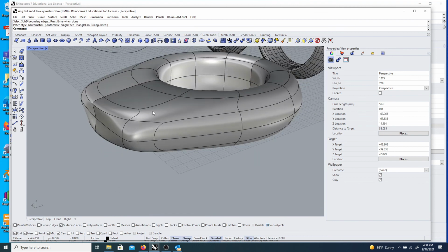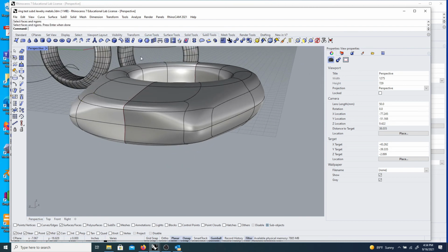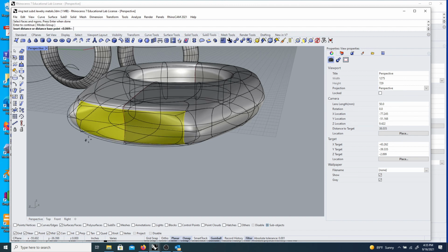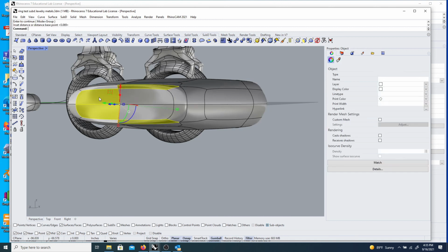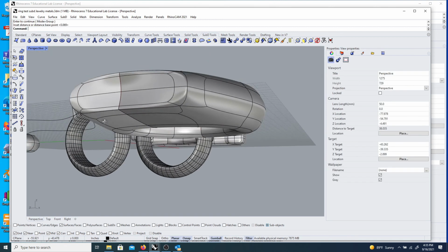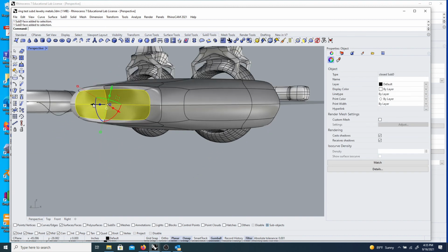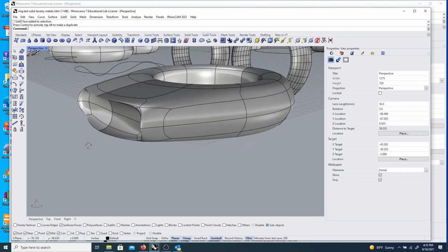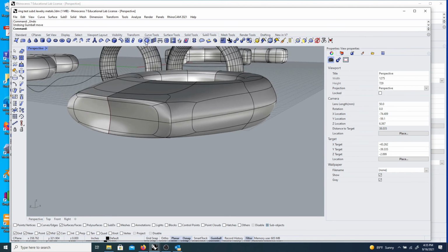And then I can even do this weird thing. It's insert sub D edges. So I can take that and create another face on the inside there, to continue working with this if I wanted. I can push that in, create a cavity, or I can inset that again even.